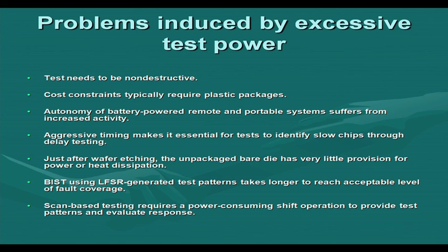Still, since we cannot skip over the LFSR's output, we have to generate those patterns and apply them to the circuit, so that will consume power. So, this is one issue with BIST testing. On the other hand, if we have scan based testing, both for the ATE based approach and the BIST based approach, there will be a shift operation.